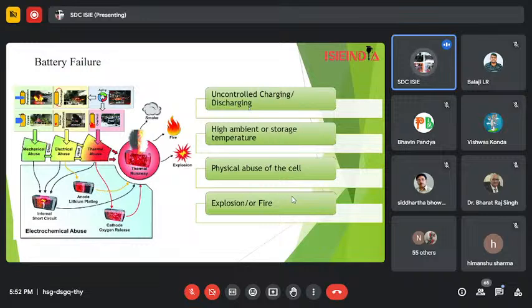Again, if you are not properly maintaining your battery pack's ventilation, if you are not refilling all the thermal coolants, if you are not taking proper care of them, it will put stress on the thermals, and that leads to thermal abuse.